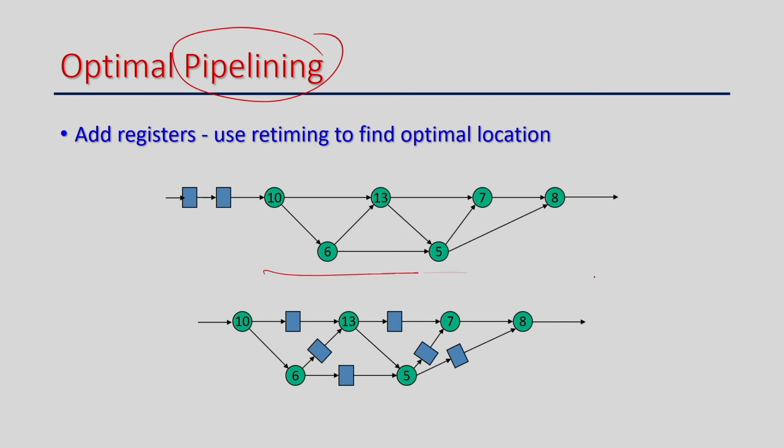So, I know this is my circuit, and this circuit has to be pipelined. That means you have to add a register layer, right. So, you have to add pipeline stages, and pipeline stages are nothing but a set of registers in that particular path, right. Say these are the delays, 10, 13, 6, and these are the register delays. So, I can put the registers at the input, and then I can set a target clock, say 20 nanoseconds, and then I can apply retiming. Retiming automatically adds this pipeline in proper places, right.